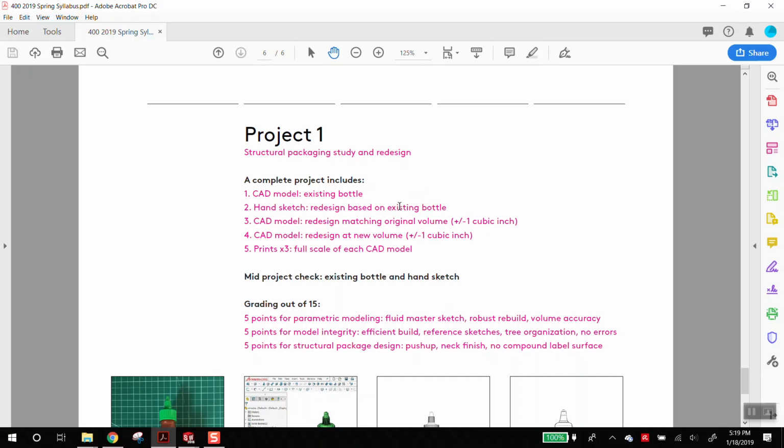If you take the time to make a very carefully designed master sketch at the top and copy aspects of the sketch throughout your model, anyone who's working on your file can just go to the sketch and make the model wider or taller by changing one sketch, without having to find in the feature where it gets wider. So it's just an efficient way of working. It's a way of saying, hey guys, all of the important information, we're going to put in a single sketch and have everything point to that. It's all about workflow.